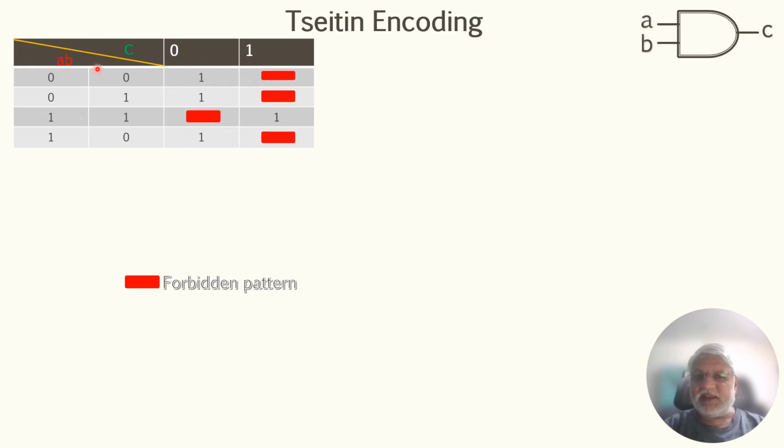Now we are representing, as I mentioned earlier, the inputs and outputs of W in multiple sub-expressions. So this can be written as W equal to, so we should take these two to get the minimized information. Just like a Karnaugh map, here B becomes redundant. So this is A bar, and here these two give C bar. Similarly, when we consider this one and this one, A is eliminated. So this becomes B bar by taking these two, and these two give C bar.